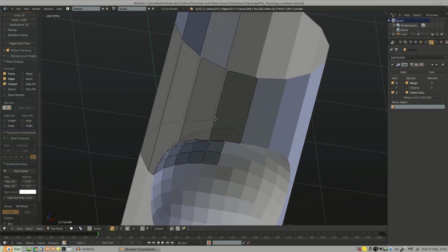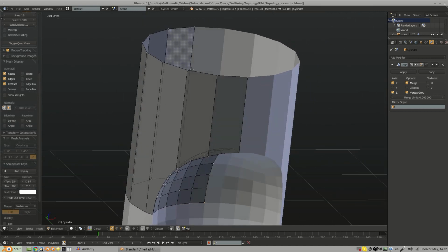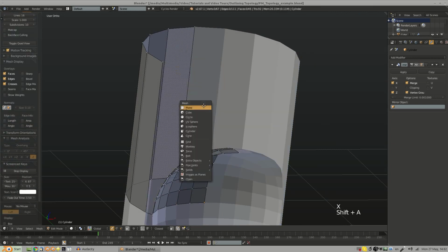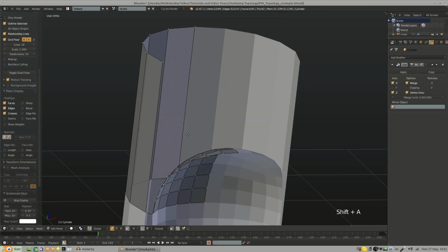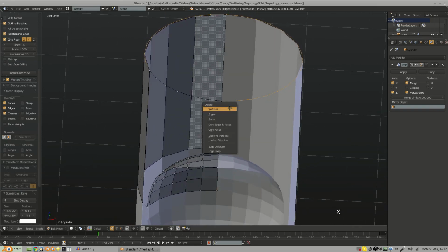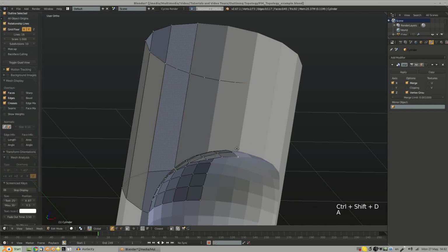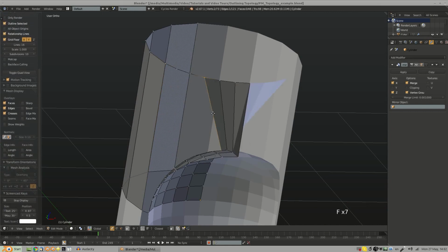I want to do something real quick, and that is I'm going to take out these vertices, add a new circle, move it up over here, and this is the default 32, so it's twice as many vertices, and I want to keep those vertices there, delete the rest, remove doubles there, excuse me, and then just fill this in. Whoops, wrong direction. Wrong direction. There we go.